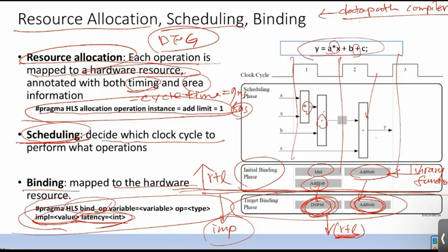So that's the pragma. For this tool, you need to know the FPGA architecture well. Otherwise, if you don't know the block RAM or the DSP, you don't know how to use those pragmas. To really optimize an FPGA design, you do need to know the FPGA architecture, and in particular the FPGA device you're going to use.